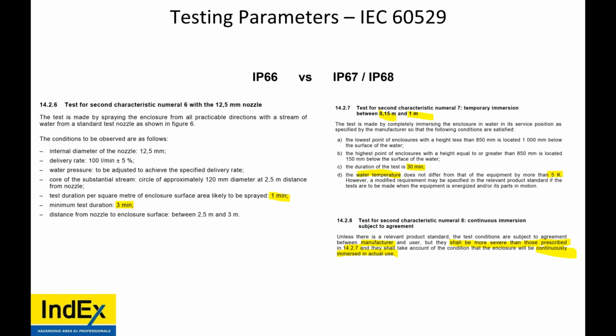Somebody asked or said that flame proof and explosion proof are the same. No, they are not. Different testing requirements. One is based off of EN IEC 60079-1, while the other one is UL 1203. So this is going outside of IP ratings, but they are not the same.